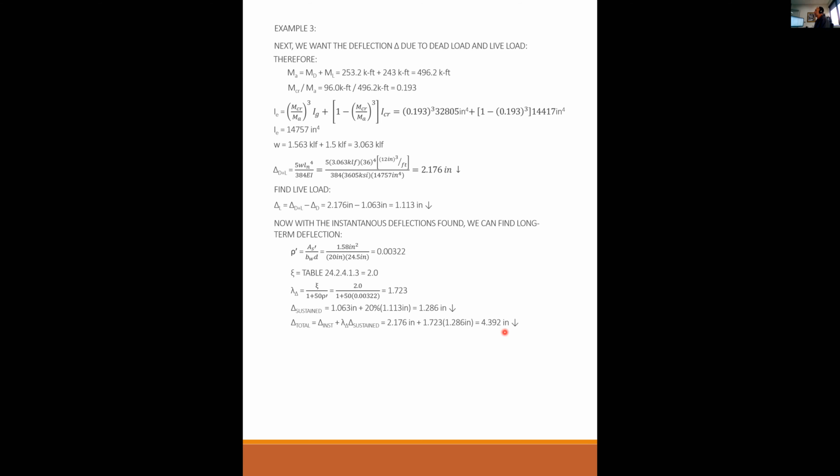But you did ask a good question. Why did it grow so much? Well, the reason that it grew so much is because of creep. And because these deflections are actually kind of big. 1 inch and 2 inches is kind of big to begin with. I really should not have designed a structure that would have that much deflection on day one, knowing that in 5 years I'm going to get to something like this, right? So what would I do? Let me turn it around. How could you make this better?